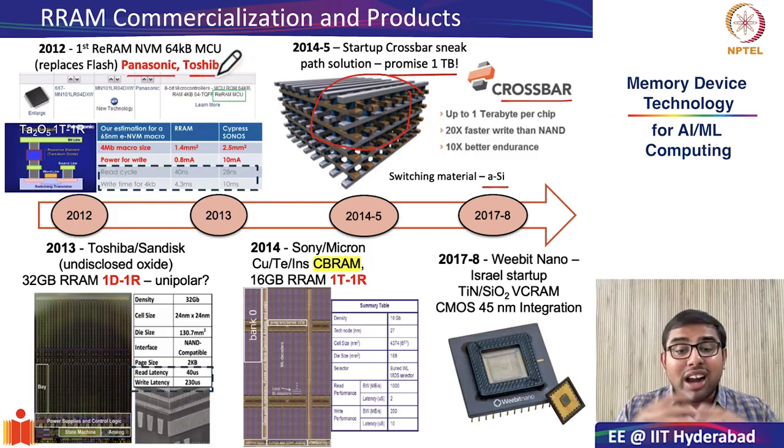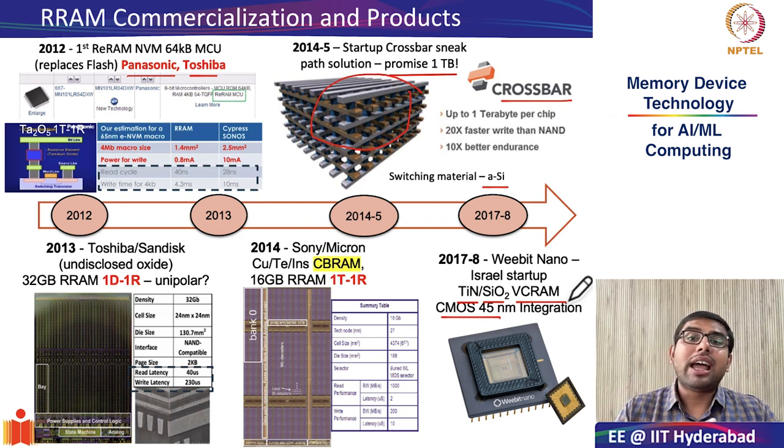Also, another startup success story is coming from Weebit Nano. This was an Israeli startup in association with the French lab CEA-Leti. They had shown CMOS integration at the 45 nanometer node for titanium nitride SiO2 based RRAMs, and they too are showing a lot of interesting applications for embedded memories.